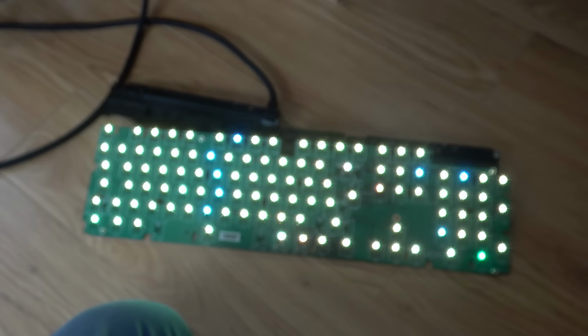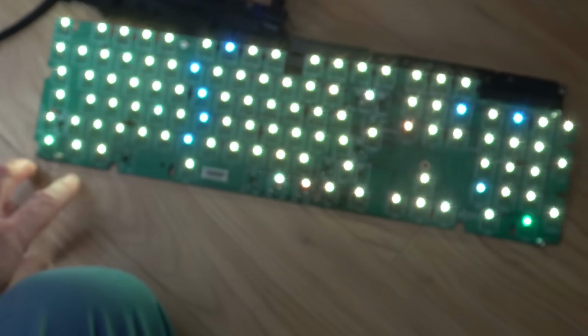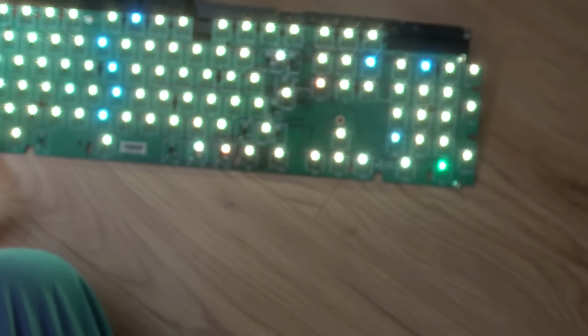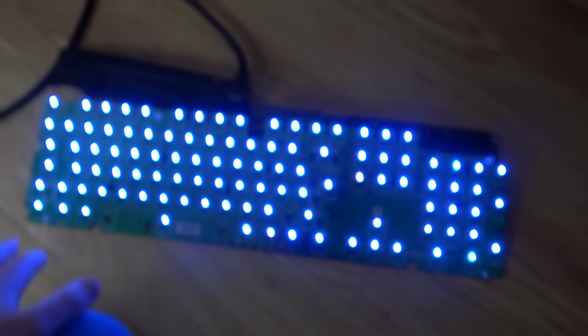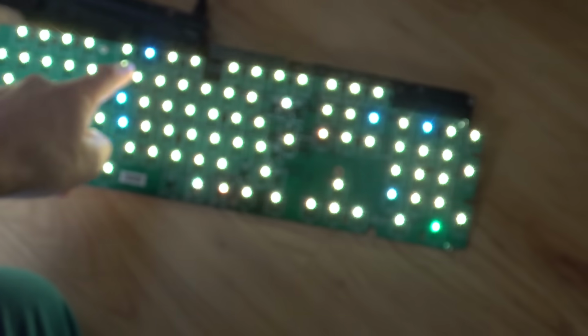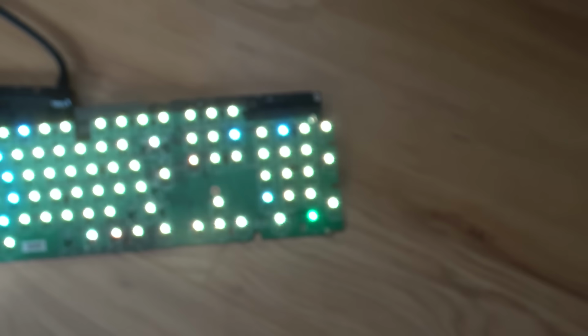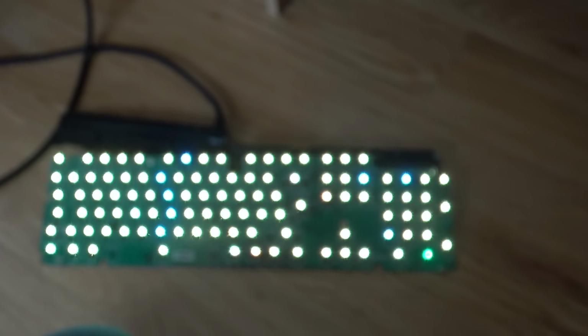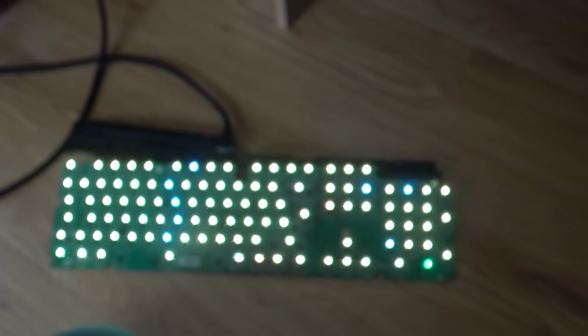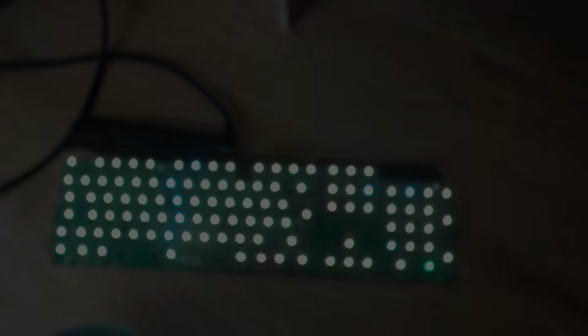We definitely had faulty LEDs. Mind you, to be fair, the ones down here, they're now okay, aren't they? Let me go to blue. So those 2 are fixed. Right, I'm going to mark up these ones here. Here, here, here, here, here, and here. And see on diode test, do they read different than the others? Maybe there's something else gone on here as well. It's very strange.